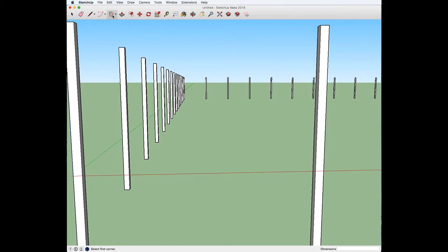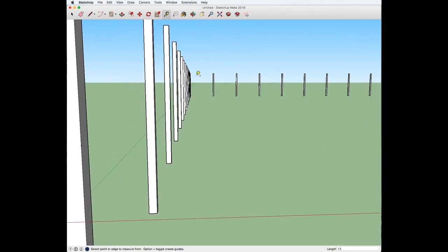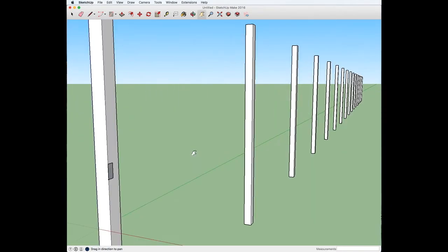So we're going to grab the rectangle tool, and here's the ground level, and we have 5 feet above. So let's say we want to do a rail 1 foot up. We could just use this tape measure tool, go from this point, and type in 12, enter for 12 inches. And now we have a little guide mark right here. Then we can grab the rectangle tool, start right there, and rough out a 2x4. And then we just start typing in the lower right. So we're going to type 3.5, comma 1.5. And there's your 2x4. There we go.